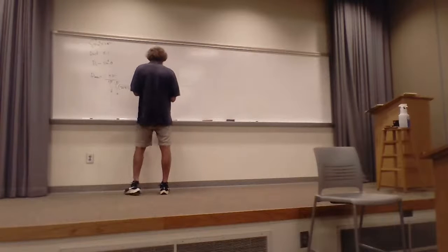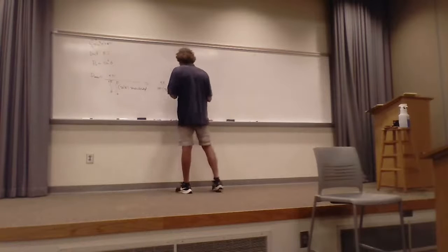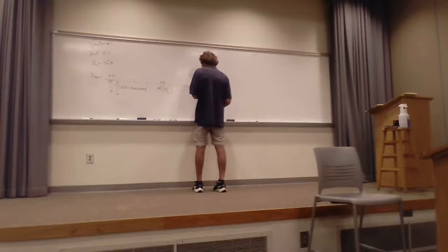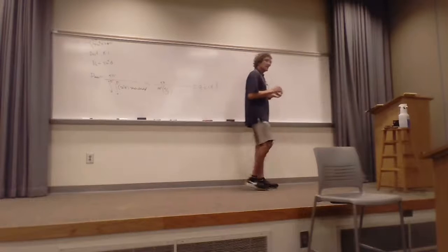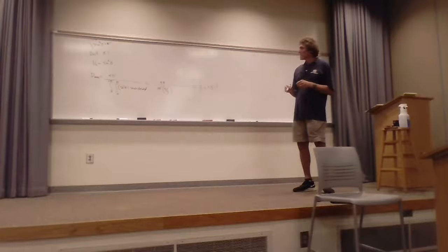So this is going to be times 4/3. And lo and behold, you see the pi's cancel, right? The 4's cancel, and I get 3/2 or 1.5. And then I'll tell you this. That is the gain. I'm sorry, that's the maximum directivity of a short dipole. I'm just going to say that.